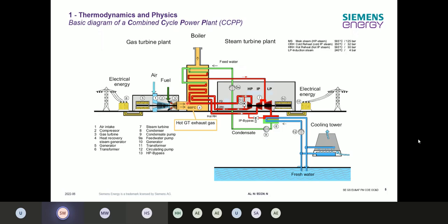And in the superheater, of course, we only want steam. From there, we get into the turbine. In front of the turbine, there are, of course, an emergency stop valve and a control valve to protect the steam turbine.